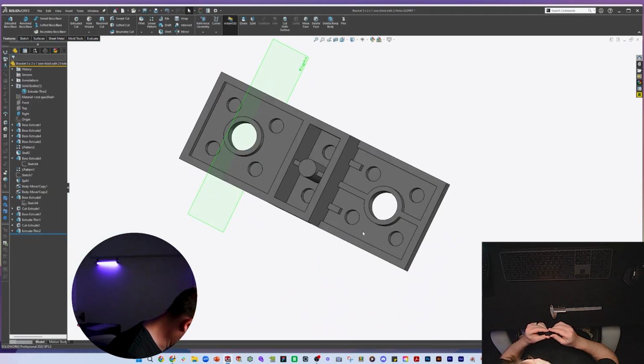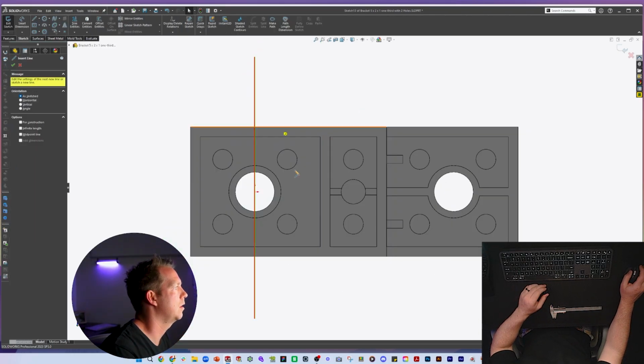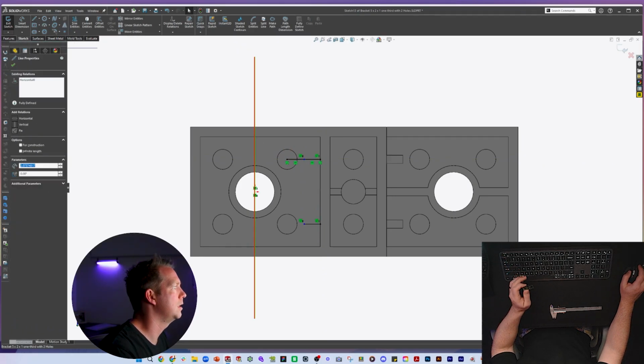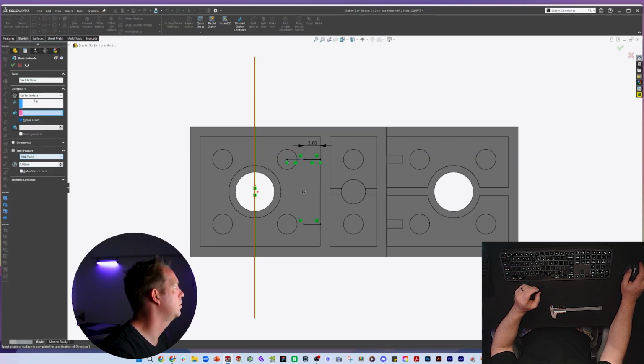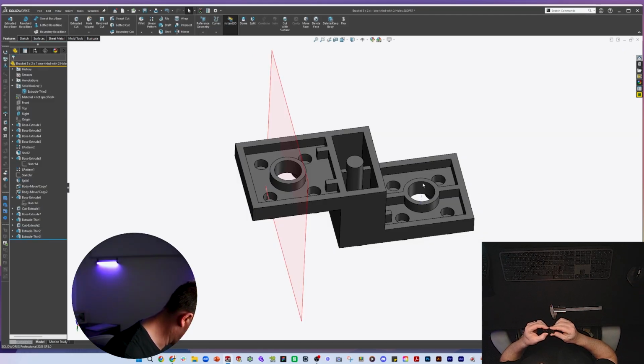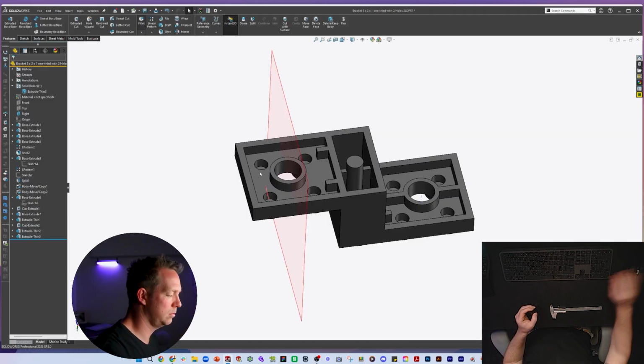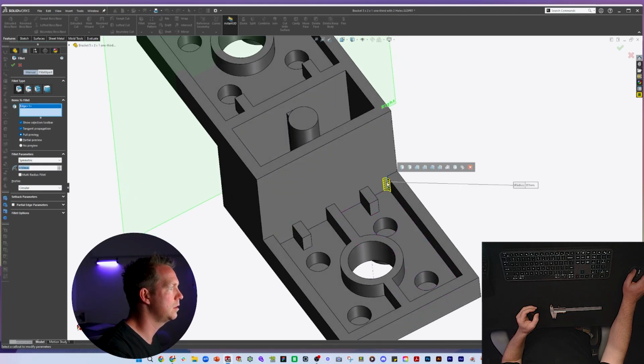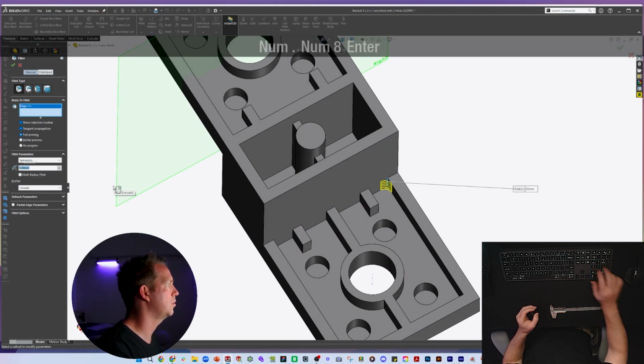All right. And we have the same ribs on the top one here. So again, I'll do a line from here, and I'm splitting that line. All right, so this part is for construction, mid-plane, up to surface, up to this one. All right, and then we want to add those fillets at the bottom. Very small, probably a material flow type thing. Just on that edge, maybe it's 0.8.